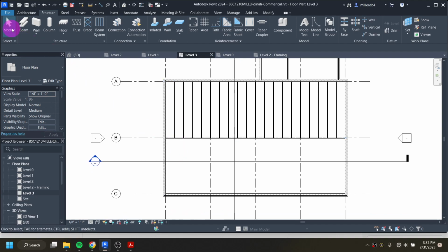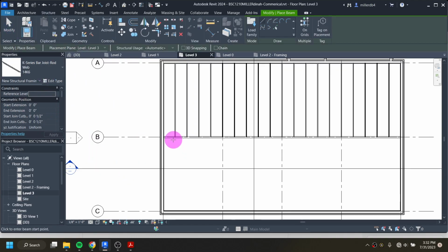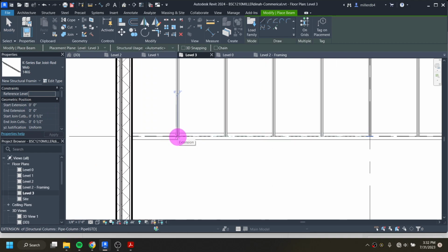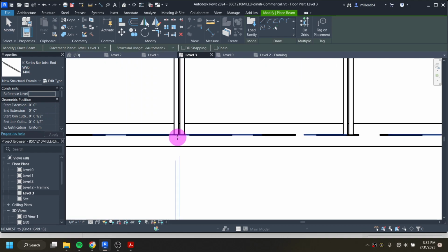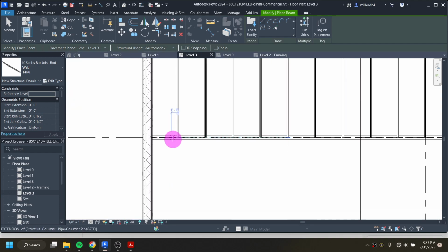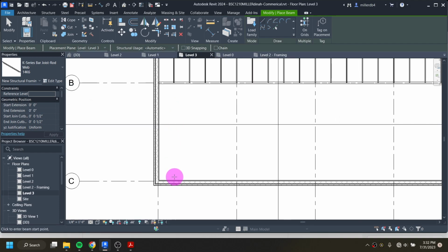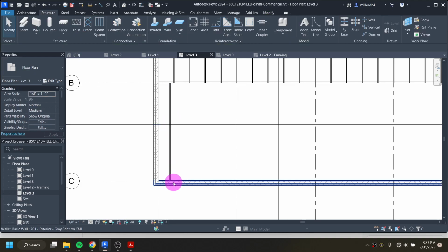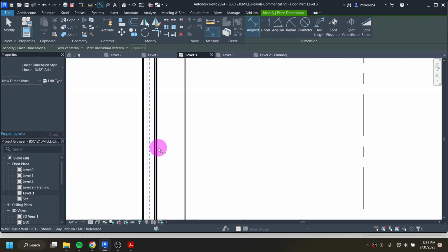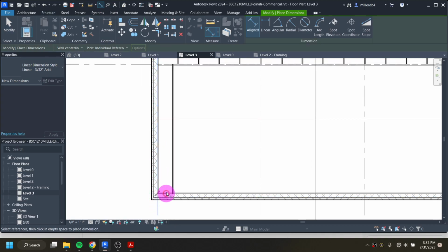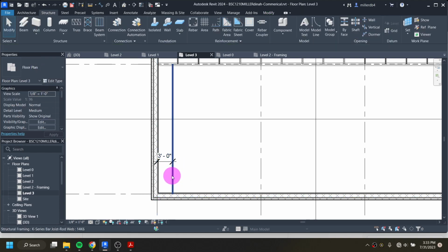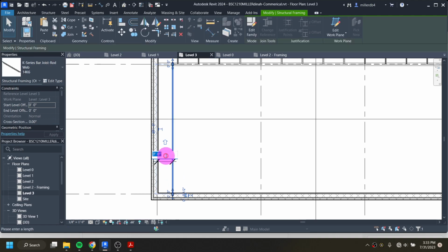Do another one right underneath it. So I'll do beam from, is there a way I could get that nice on the center there too? Just so I don't have to measure twice over. Well, I guess not, no. So I placed a beam then from this one over, dimension, from my grid to its middle, click to place it, hit escape a few times, click on this one,